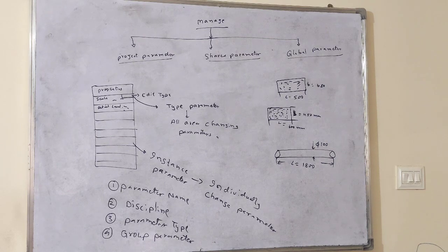But if I select this grid again and go to edit type and change something, for example the end segment weight, which is right now 1, and I change it to 2 and click OK, you can see this grid is already 2, and if you select the other grid and go to edit type, you can see 2 is there.